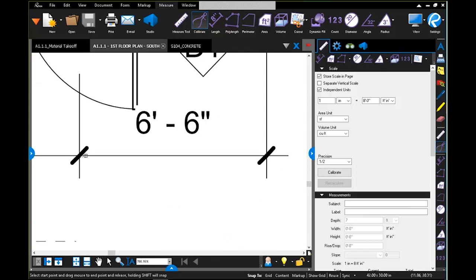But before I do that, I want to explain a couple of things that's happening here. If you happen to follow along with me and you have a second monitor and want to follow along, that's awesome. But you probably have a PDF document that's open and it's not snapping exactly how it is on your screen. And that's probably because you're working with a scanned document. So there are two types of PDF documents out there. We have a vector PDF and a rasterized PDF.